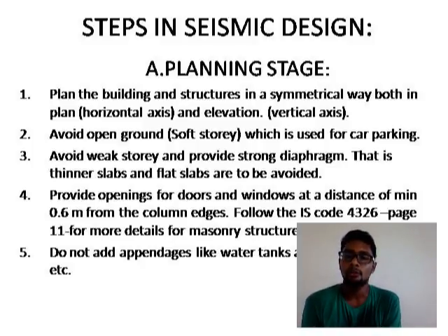Avoid open grounds. If the storey is raised to more than 10 to 15 meters, the foundation has to be strong. It is based upon the type of soil which you find in the site. And providing of openings: the openings which we give, such as doors and windows, should be a minimum of 0.6 meter away from the column edges, so that during the earthquake load, the column gets more stiffness when the openings are avoided.